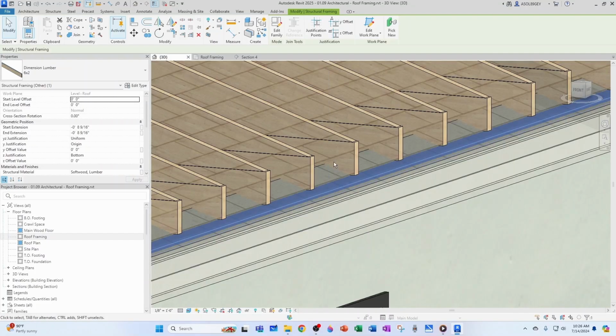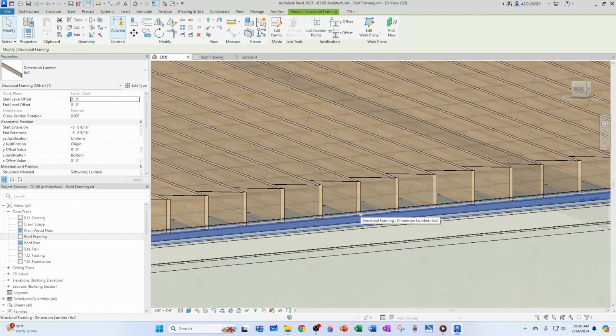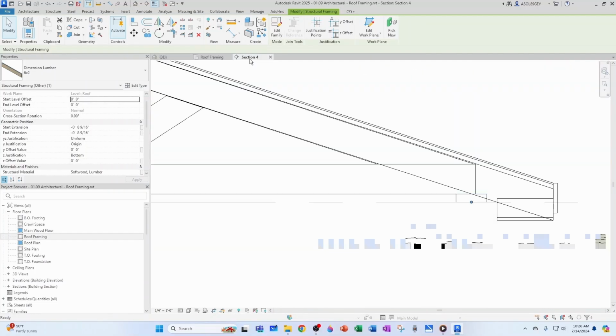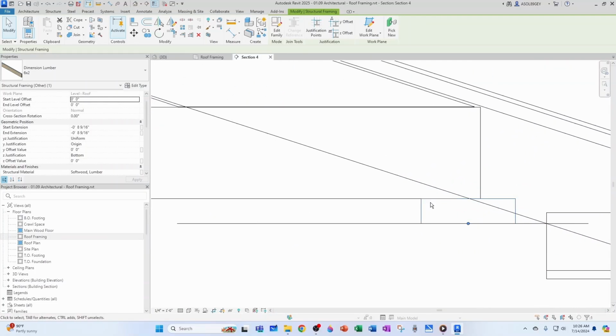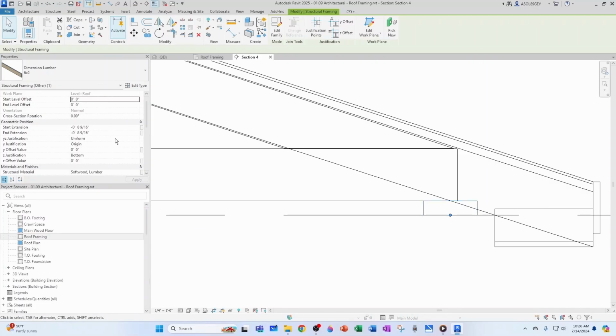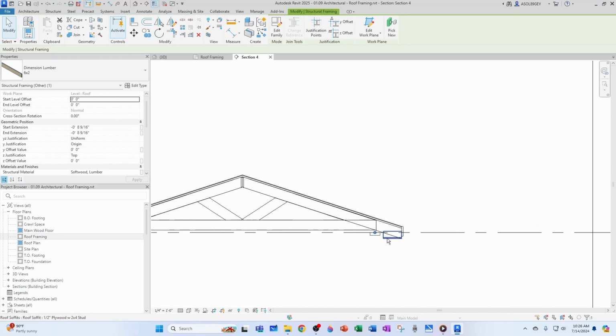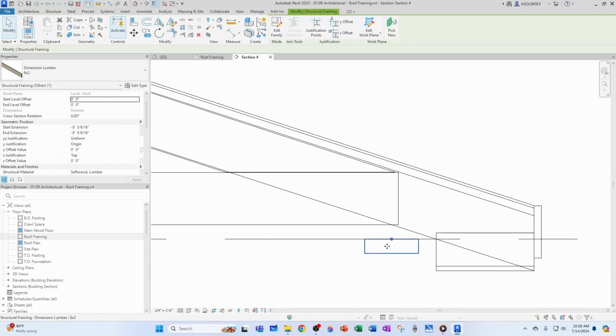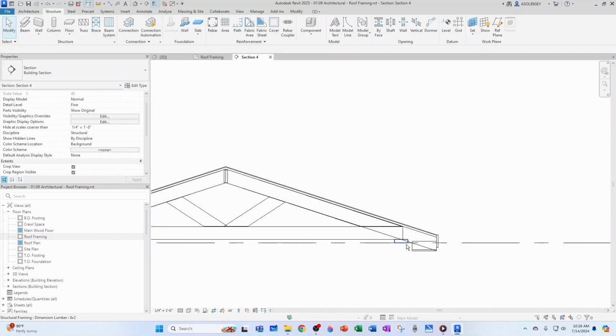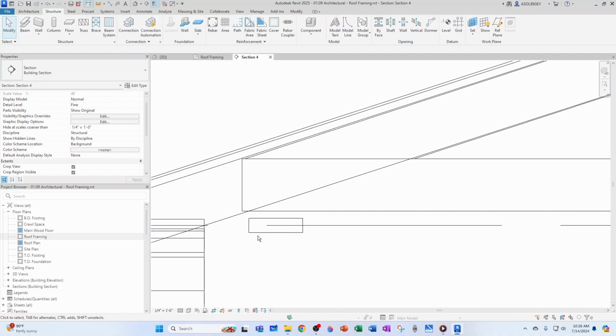And now if you go to our 3D view, this is sitting perfectly under the ceiling joist. You can see that clearly in your section. Here it is, see? And even if it wasn't, this one is easily fixable, because typically a common issue is that by default, this is set to top, and then you would have your structural member with the top aligned to the reference level, which in this case is the roof. So you would fix that very easily just by coming here to the Z justification and changing that to bottom, okay? No issues there.